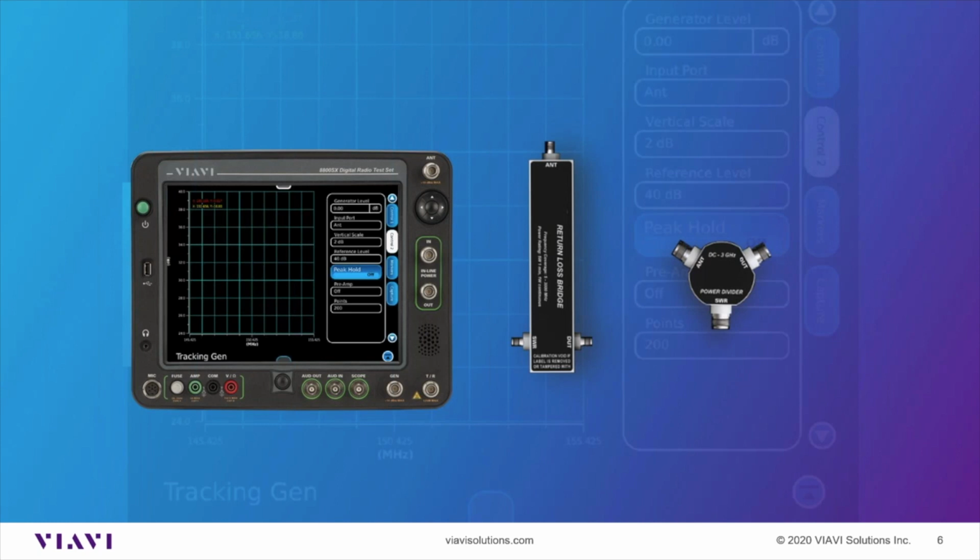If you're at a site sweeping an antenna, the return loss bridge is much less susceptible to that. So the bridge is a better choice in a high RF environment. And again, the 3550 does support both methods.